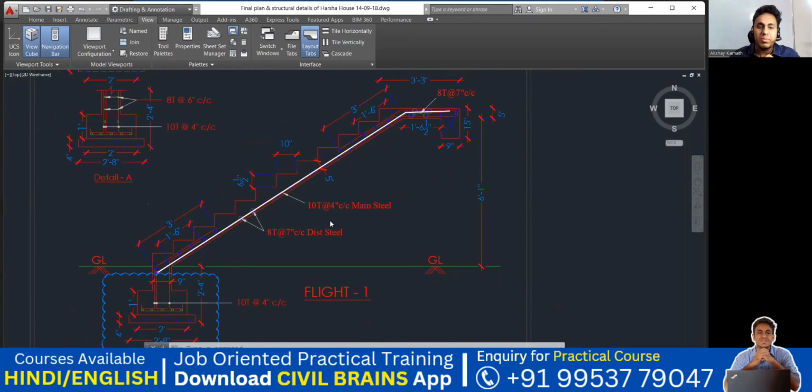And which diameter of bar are you supposed to use? You're supposed to use a 10 diameter bar at 4 inches center to center spacing. And the dotted one, the blue color, whatever you can see, they are your distribution steel. That is an 8 diameter bar at 7 inches center to center spacing. So 7 inches center to center spacing you're supposed to provide. Got it? So this is how your reinforcement is to be given.